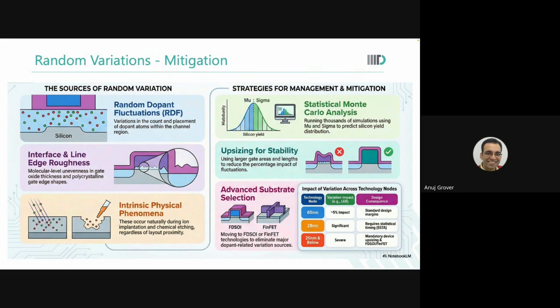The device sizes are by nature, by design, small. But despite this very strong constraint, you continuously see where you can increase the lengths, where you can increase the width, so that the benefit of reduced mismatch can be maximally extracted. Are you with me? So that is the first thing that you do.